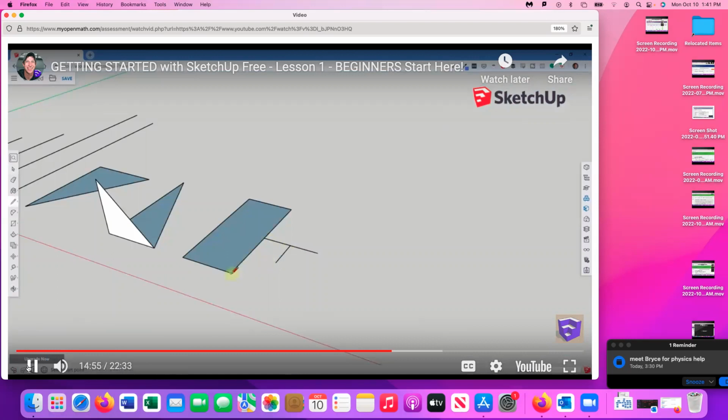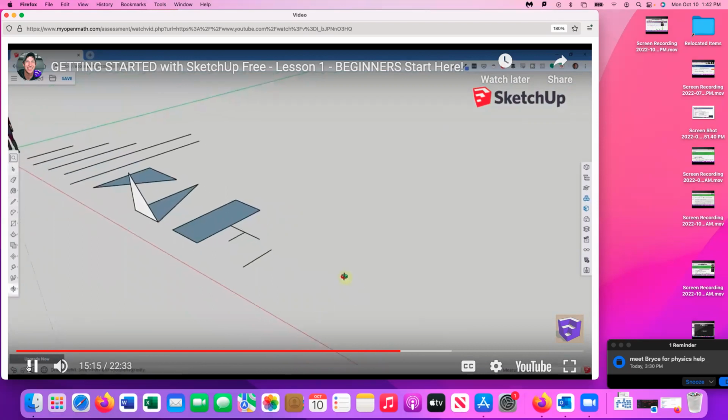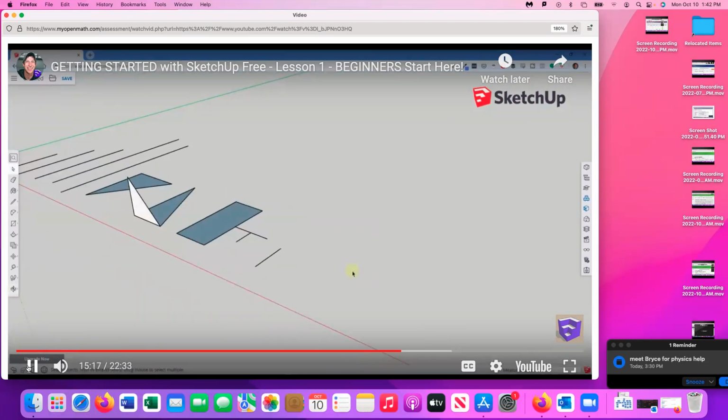There's different inferences that you get by hovering over edges. So for example, if I hover over this edge with the line tool active and then I move my mouse, you can see how I get a dotted line coming off of that end. That's kind of indicating that if I was to draw a line from this point, it would be level with the point that I had kind of moused over. And so we can talk more about those in the future, but those give you kind of an idea of what you're drawing along.